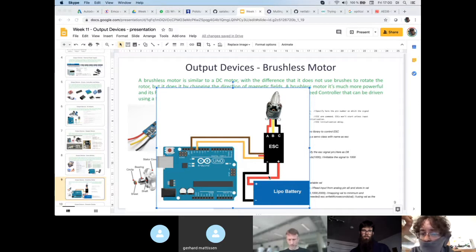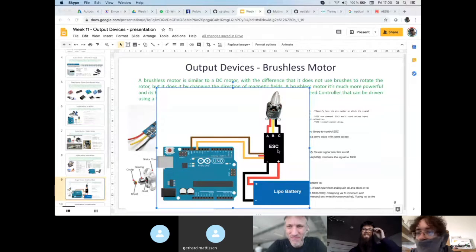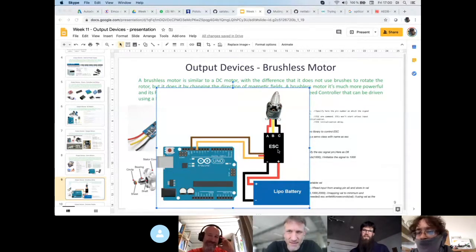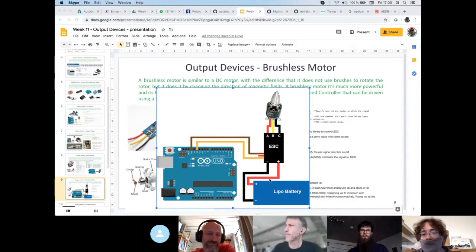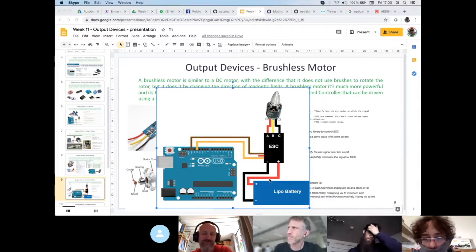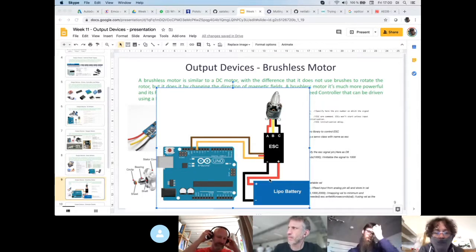In my final project, I slightly under-dimensioned these traces that go from the battery to the motor speed controller. And what happened is that the trace exploded while the drone was flying. So the drone, guys, was just going crazy and falling down almost immediately. So in your case, I don't know how the dissipation is, your DPV, but you need to dimension this really carefully. Also, they can become very hot before exploding. So this is the electronic speed controller.